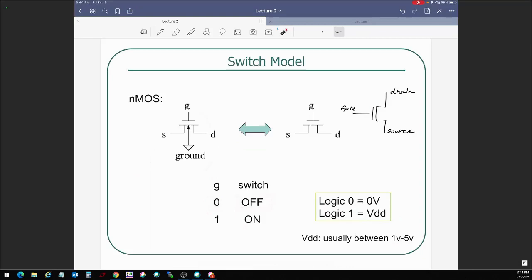So let's take a look at this table here and try to draw some even simpler diagrams. What does this 0 indicate? Well, that simply indicates that the voltage at the gate with respect to the source is less than some threshold voltage VT. And when that happens, the switch is off. There's no N channel. What does switch is off mean? Well, the source and the drain terminals are disconnected. So the one thing that is very common here is you are actually connecting or disconnecting the source and the drain using the gate terminal, right?